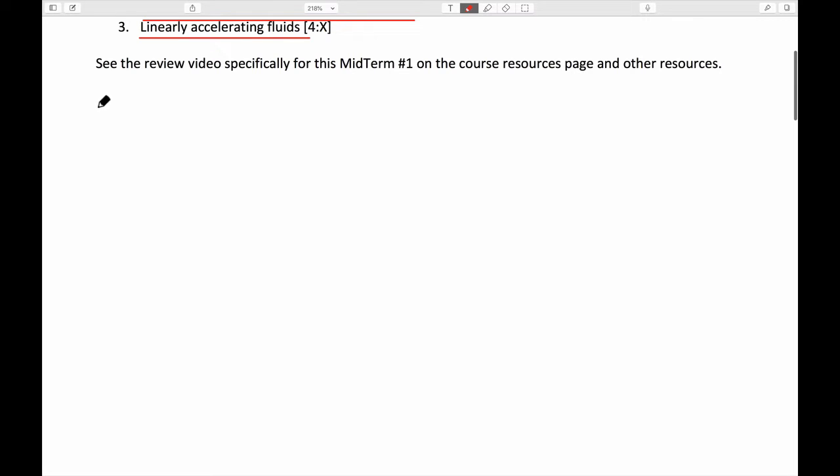In terms of fluid properties, you'll need the ideal gas law. Pressures are related to density, ideal gas constant, and temperatures. We know that pressures and temperatures must be absolute. So make sure that when you use those, you're using absolute temperatures and pressures. And you can also write this if you want in terms of a density, which is a given mass divided by the volume of that container, if you like.